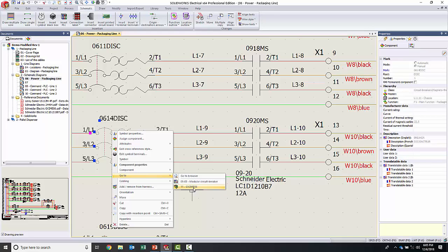If you place it 10 times in a project and wanted to know whether this is disconnect number 1 or disconnect number 10, you have no way of determining that without additional steps in SolidWorks and breaking the references a bit to tell it that it's a separate instance, where normally it would just say that it's that one 3D model.